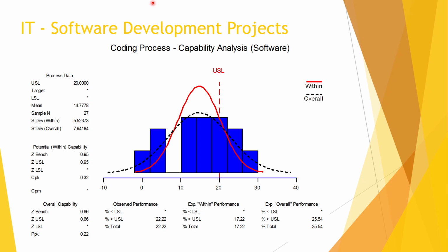You should also know a disadvantage of the PPK index is that it only represents one side of the process curves and tells you nothing about the other extreme. For example, the graphs below display processes with identical PPK values. However, one violates both specification limits and the other one violates the lower specification limit. To avoid mistakes, do consider all indices along with a graphical summary to draw meaningful conclusions.